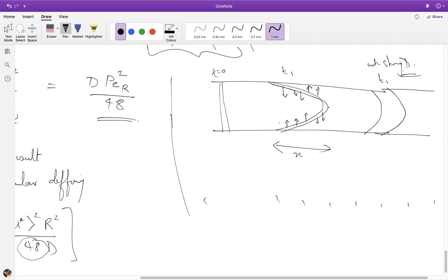So although the slug itself is thinner locally at low diffusivity, it gets stretched out much more by the non-uniform velocity. Whereas with high diffusion, the slug locally looks thicker, but the extent to which it gets stretched out is less. So the effective spread in the x direction is much less than if you have low diffusivity and the velocity just keeps on elongating this strip.